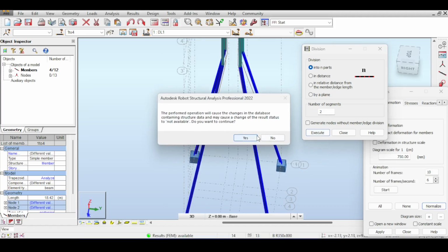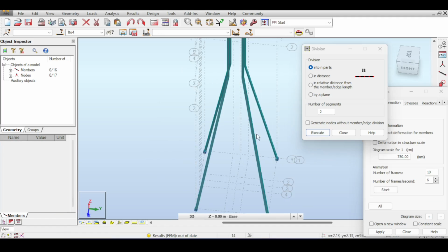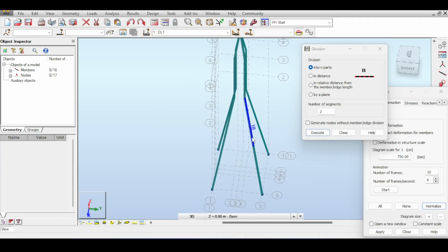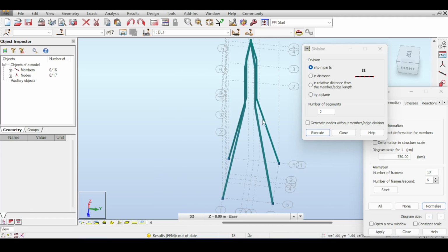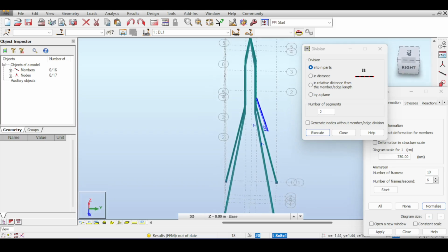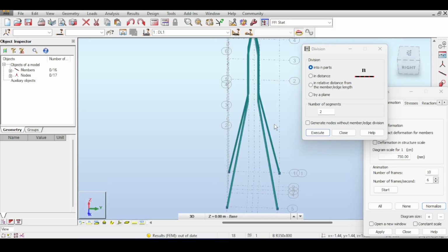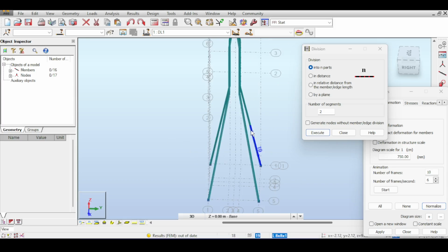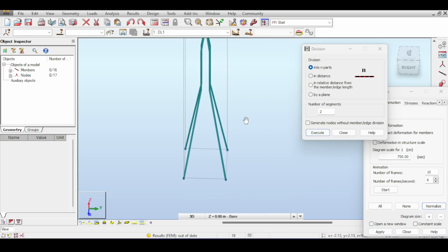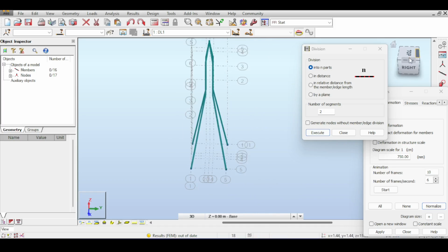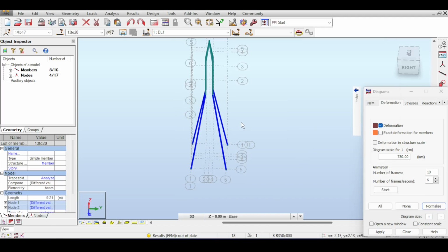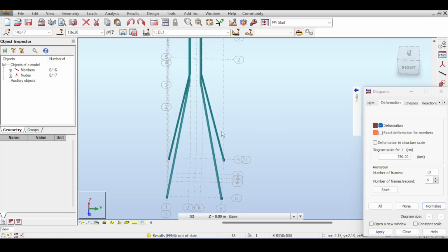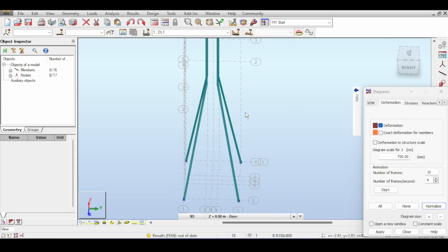So if you execute this now, you can see that now there are nodes included, and now each of those members has been split into two pieces. I want to split it into two pieces, not because of structural stress reasons, but because of practical reasons. Now, truth to be said, I wanted to split those into 7 pieces, but because now I have 2, I cannot split to 7. I need to split to 3 and 3 because I want it to be homogeneous when we split. Because look, how can you split this to 7, this to 4, and this to 3? It doesn't work. It must be symmetric somehow. So you can split it into 3, 3 or 4, 4.